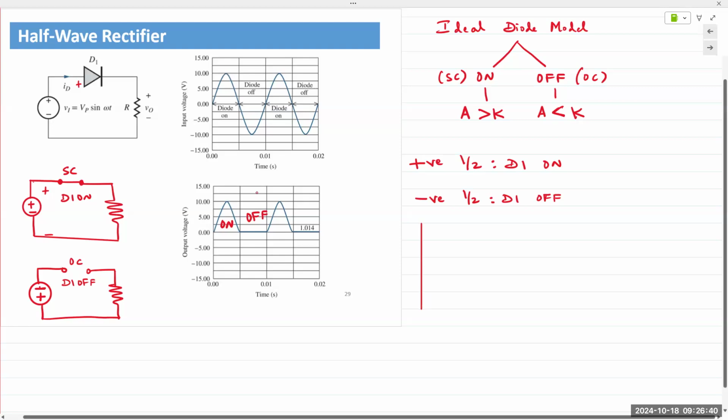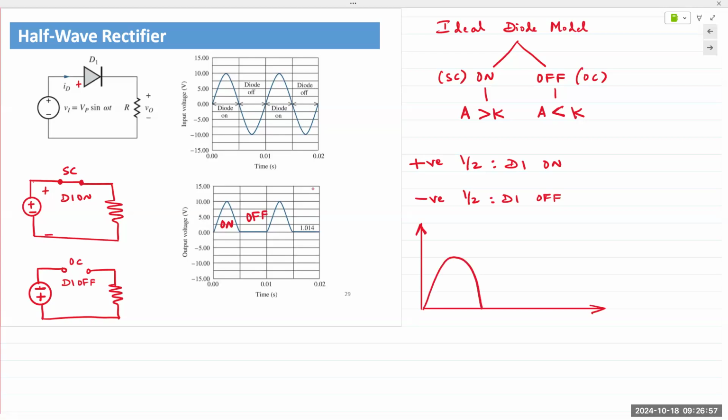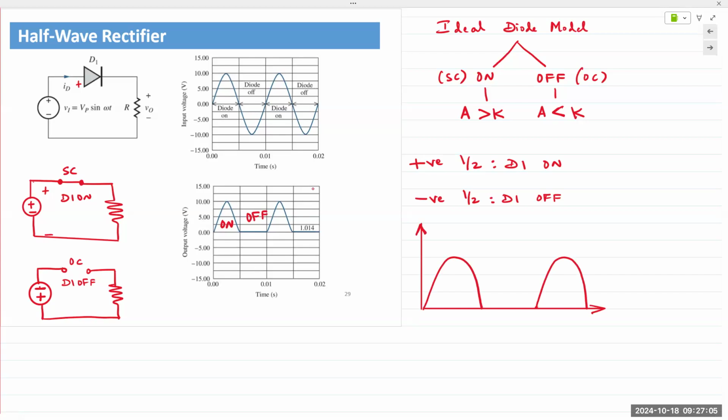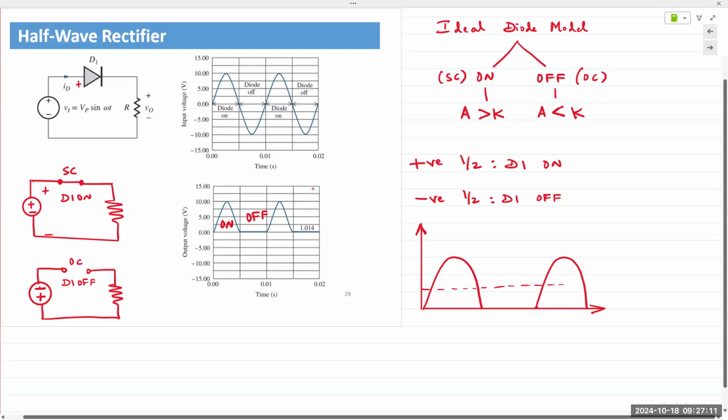Before we do that, I can point out that any waveform can be said to have a DC value. So in this case, if you have a waveform that is like this, 0 all the way through here, think of these as, let's say, mountains of dirt, and you flatten them out. Somewhere around here. And so this would be the average value, or average DC value of the waveform.